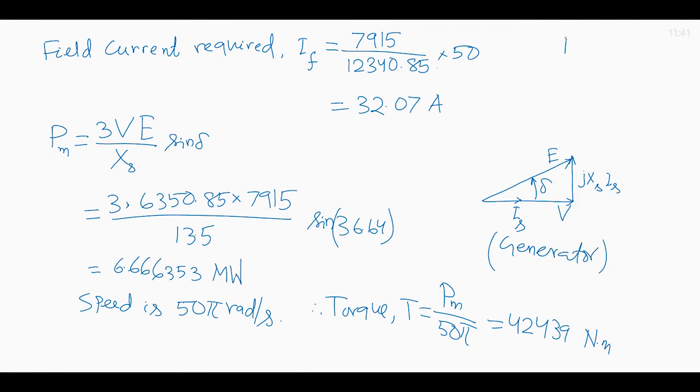For unity power factor motor operation, this is V, this is IS, this is jXS IS, and this is induced EMF E, and this is delta, the load angle.